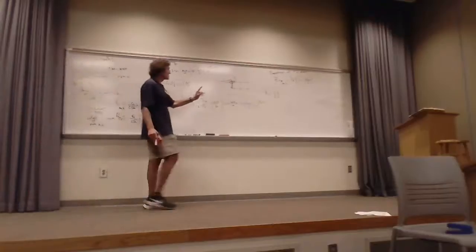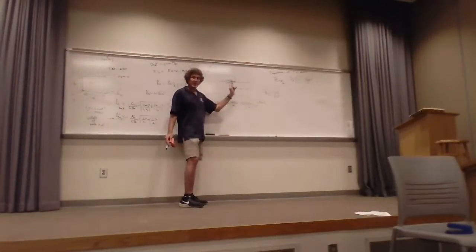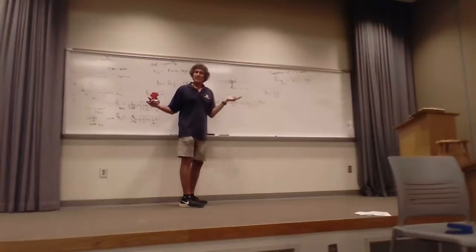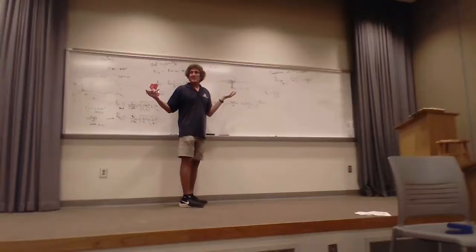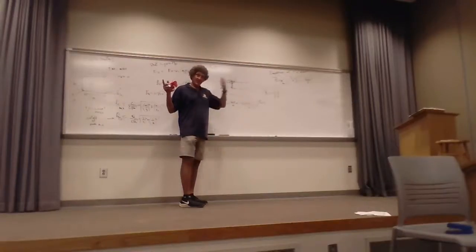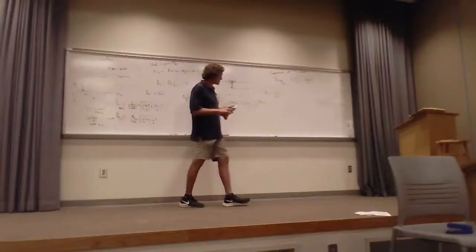When you're putting energy into a waveguide like this, if you're at a frequency so you can develop the 1-0 and 1-1 mode, both will develop. All right, and the thing is, I didn't talk about this yet, but the velocity that they propagate is different, which means you would get corruption of the signal integrity. If that happens, then everything's garbled at the other end if you're trying to communicate, because then there is nothing that's going to be coherent about that message.